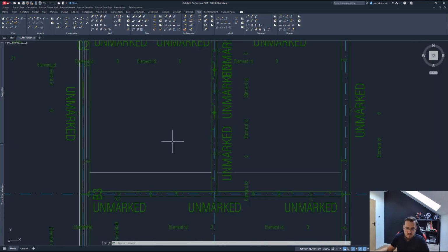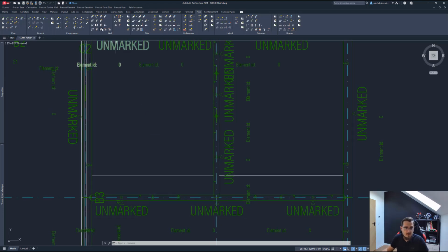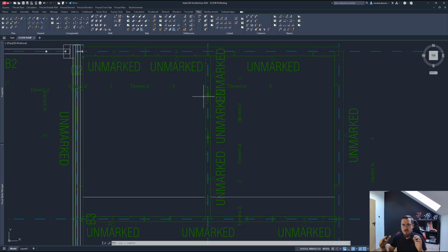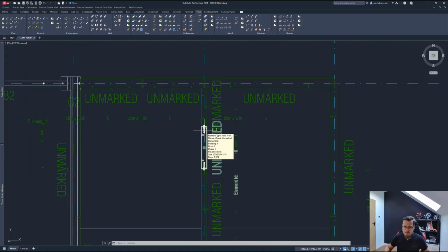All right. The other way of doing that would be to do it manually. That's casting material templates, right? So we can select multiple walls or multiple elements in the project, and with that, the program will automatically look for any types of end caps that are defined in that template and apply the casting material that's added to that. The casting material can not only be loops like here, but it can also be, for example, a type of rebar or maybe channels for connecting other elements. Basically, any casting material that you can think of and create within the AutoCAD interface and have a 3D model of, then you can use that as a casting material template, right?